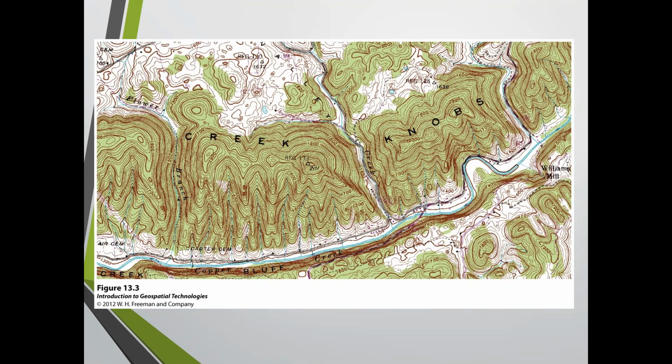And the typical way, I'm sure most of you guys know this, if you want to determine what the interval is between contour lines, you look at your two major contours. So if I have 1800 and then 1900, the difference between that is 100 feet. And then I count the spaces between all the contours. So there's 4 contour lines between, but there's 5 spaces.